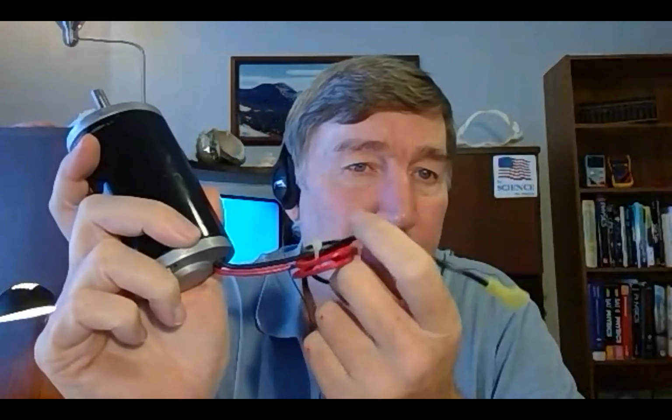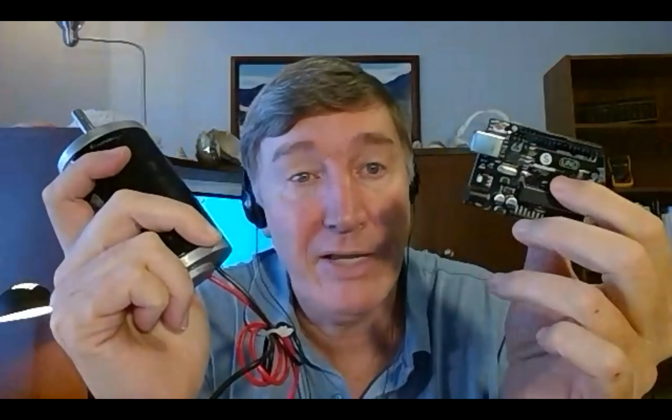And also, this motor requires a lot of current. When you hook up this motor, the current is not going to be measured in milliamps. It's going to be measured in amps. This thing can pull 2, 3, 4, 5, 6. In fact, this thing could even pull like 30 or 40 amps under certain circumstances. And there's no way in the world that this poor little Arduino can put out even 1 amp, let alone 10 amps.